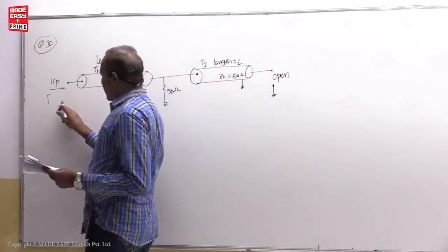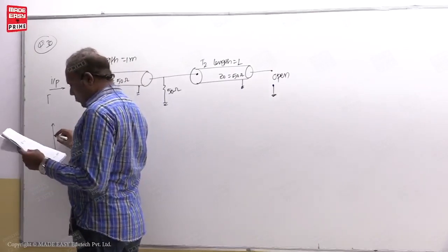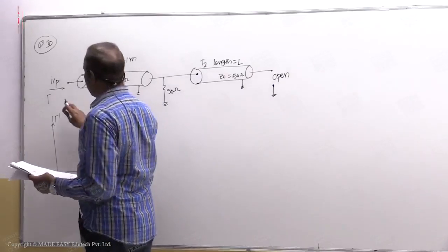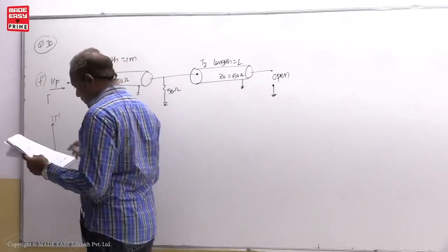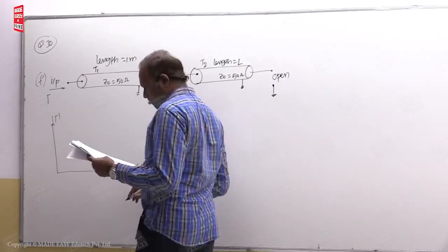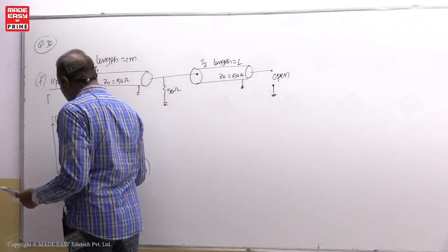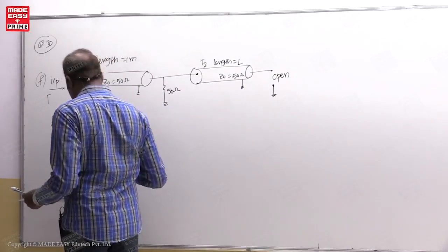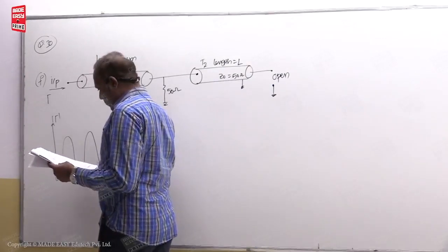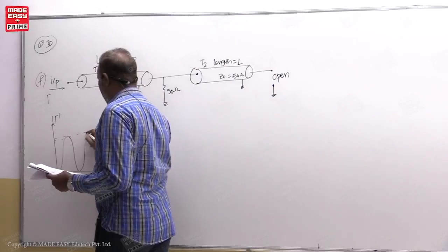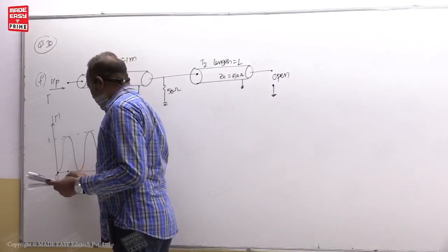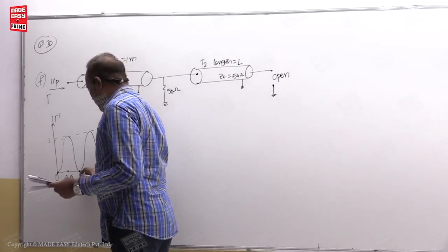Now this reflection coefficient is there. That is the modulus of reflection coefficient versus input frequency. Here the input has some frequency, given in gigahertz. So now this waveform is going like this, and here 0 frequency, and he has given the reflection coefficient magnitude equal to 1, and here it is 0.5, here it is 1.